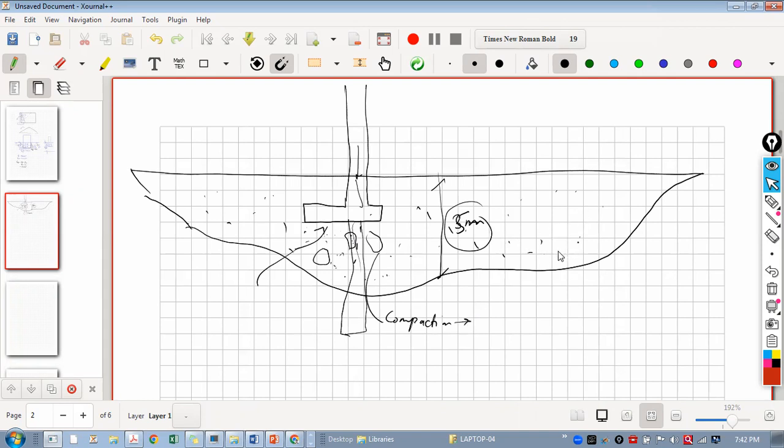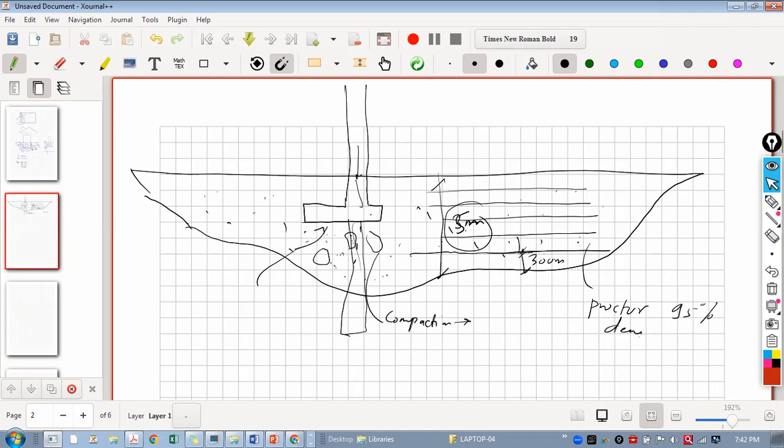See, generally such filling is done in layers. The layer is generally 300 mm or 1 foot. Then there is a second layer, then compaction, third layer, compaction, fourth layer, compaction, fifth layer, compaction, and the Proctor density is checked during the compaction, which should be 95%. And then you can raise such foundations, but for smaller structures only, not high-rise buildings.